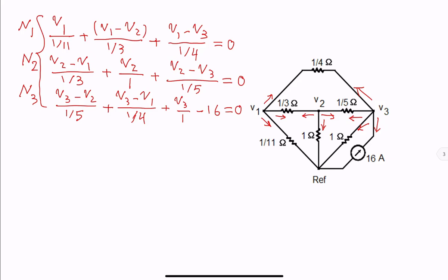If we use the currents leaving the node equal to 0, we can quickly check for a sign mistake. Through the resistors, for node 1, we should always have positive V1 or positive V1 minus something. For node 2, we should have V2 first.